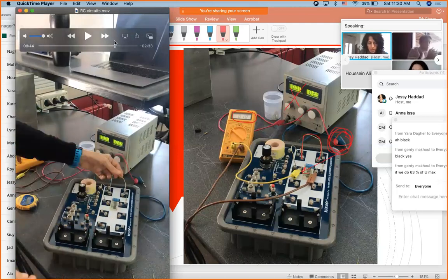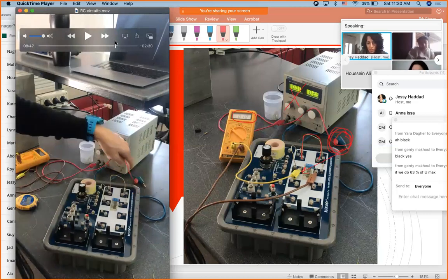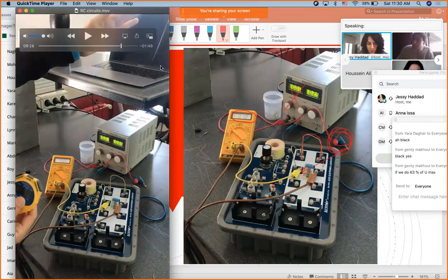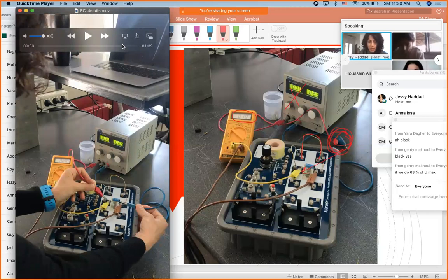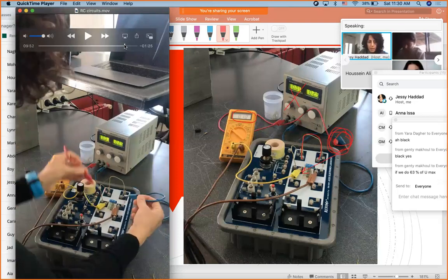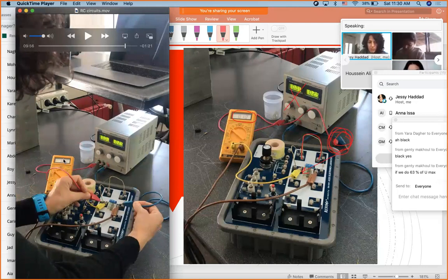Okay. All right, now what I did, I removed the battery, you see, and I closed the circuit. While talking, the capacitor will start discharging itself, and I want to time from Umax. This is why I need the power supply. You see, the power supply is fluctuating between 2.9 and 3 all the time, which is not a big fluctuation. Now I'm going to use the power supply to touch the capacitor because I want to start from high voltage. Okay, I'm trying to pause to show you that the voltage is 3. 3 or 2.9, it's basically the same.